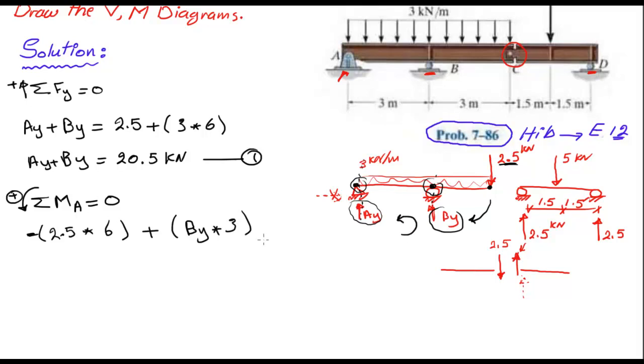Leave it this way. Okay, am I done? No, I still have the concentration of this force. The concentration of this force from the top should look something like this. It's distributed over 6 meters, so at the middle I will have a force with a magnitude of 3 times 6, which is 18 kilonewtons. So now we can forget about this distributed load and imagine just the concentrated load.